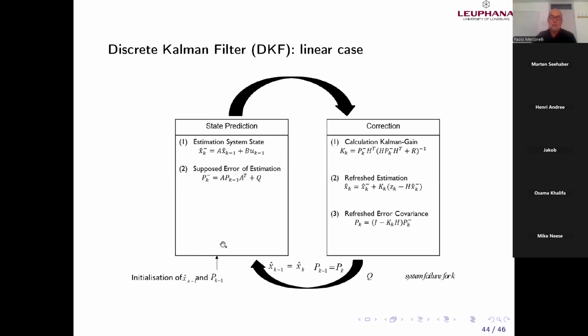To start, look at this scheme here. To start the Kalman filter, I need the initial value of the states, but also the initial value of the error. The a posteriori error is characterized by the matrix P without minus. Even though I can trust totally the model, if P0, the initial error, is not zero, the Kalman filter will consider K_k not zero.